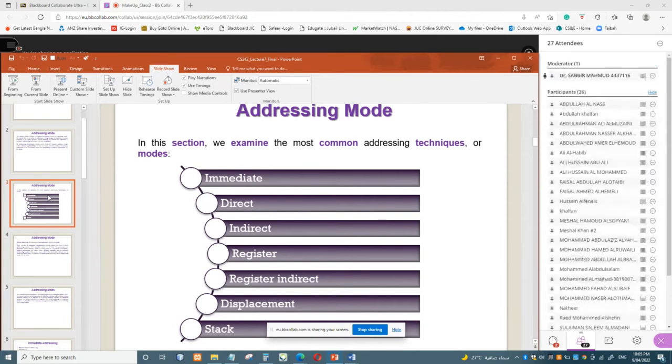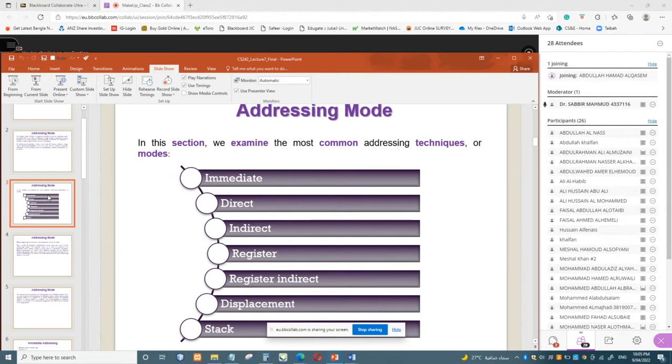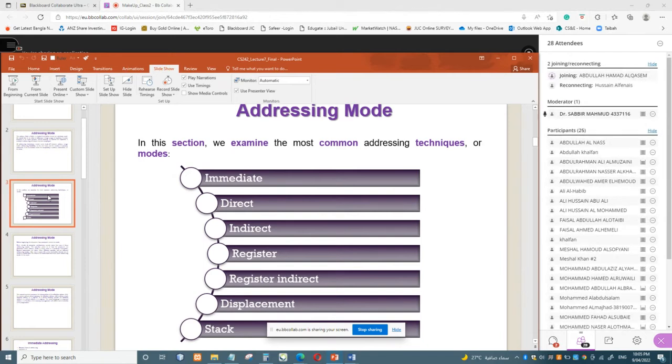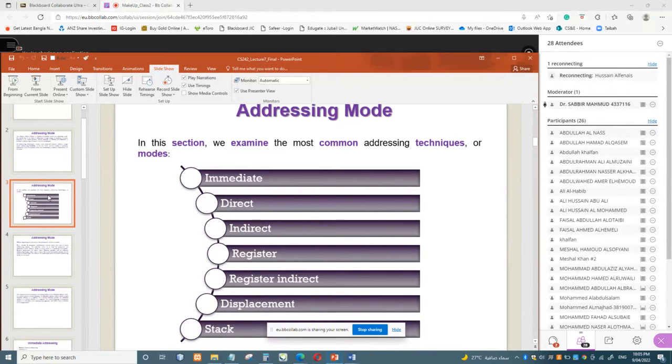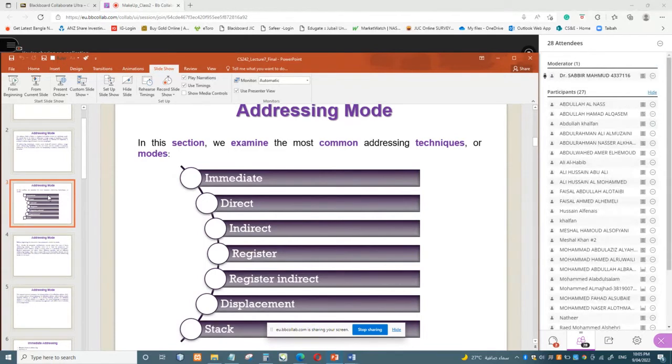So whatever the instruction is, whether it's an add, subtract, multiplication, or division instruction, or any other instruction like shift left logical, shift right logical, or the OR instruction, in every instruction you have to specify your operand, that means the data on which the opcode will be performed.